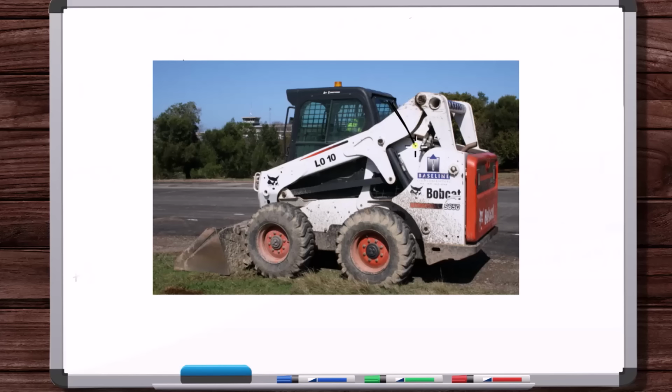But even then, if you were just doing a basic analysis of this, you would look at the cut surface and say, how is this constrained? Well, you're cutting through the material, so it constrains in every way, right? Like a metal to metal contact, it doesn't allow motion in any direction. But you would say, okay, well, it's a planar problem though, so I don't have to put reactions out of the plane. Or maybe it's not a planar problem, so maybe you put all 6 reactions, all 3 translations, all 3 couple moments. But just for basic analysis, you could put those forces at the center of the area. I mean, it's not going to be that wrong.